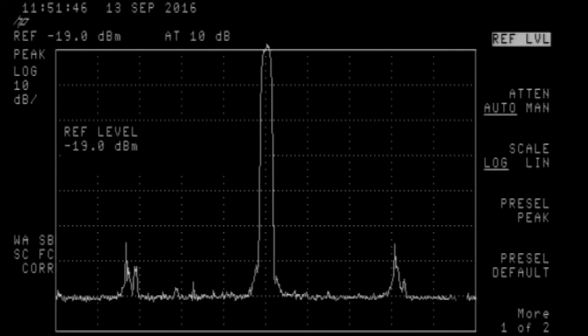And this is with the DATV-BS software operating at 1 megasymbol per second. There's a 50 meg sweep across the spectrum analyzer, so you should always have filtering after the output of the DATV-Express.